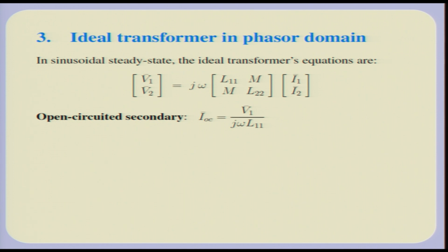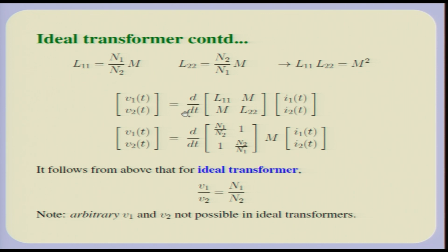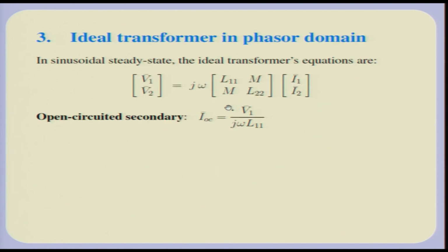Now, the equations which I showed you in the previous slide were in general, with nothing related to sinusoidal inputs or sinusoidal steady state. But if this equation holds in general, it will also hold for sinusoidal steady state situations, and therefore you can represent a transformer in the phasor domain in this fashion.